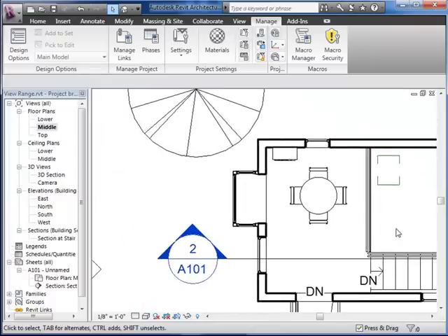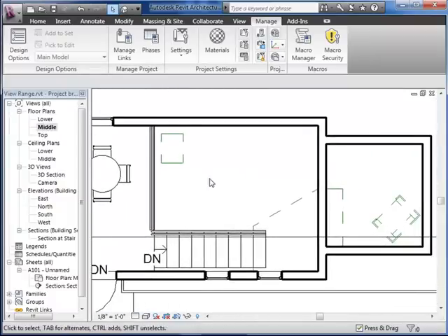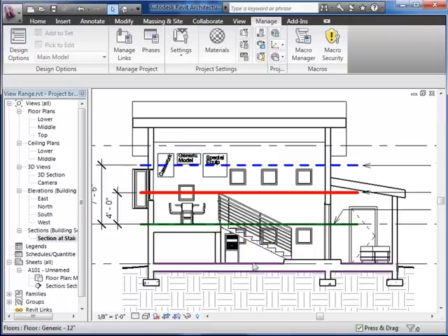And furthermore, if I zoom out, you'll notice that that effect doesn't apply just to the furnace. It actually applies to all of the items that fall within that range. If we return to the section view, what we've essentially done now is we've set the bottom of the view depth down here to the lower level, and we've left the bottom of the view range here at the middle level. Therefore, anything that falls between here and here is using that beyond pen style.